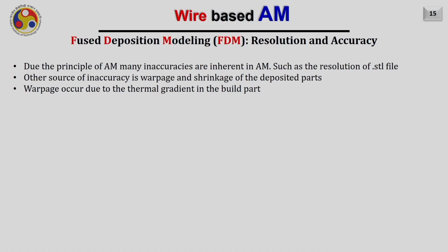You might have seen in your 3D printer, whenever it starts, it deposits material at some corner in the beginning. And this is only to achieve the steady state. So it starts at the corner, starts depositing, and then comes to the desired location and deposits the material. That excess material is just to make sure that the steady state is achieved, and now the deposited bead is coming with a constant flow rate, and your head is also moving with a constant speed. As the flow rate and the velocity of the head are constant, it is obvious that we will obtain the constant bead cross section as well.